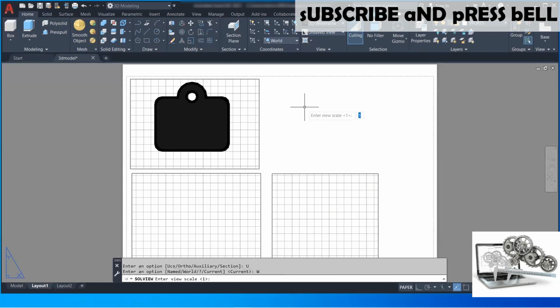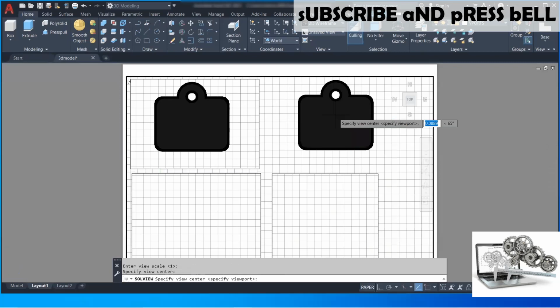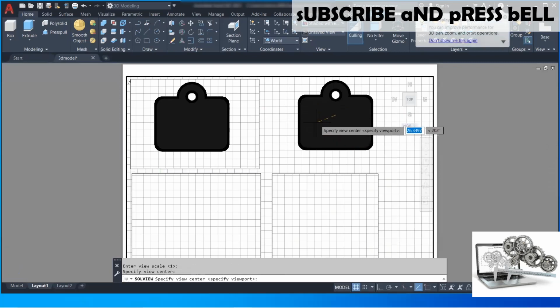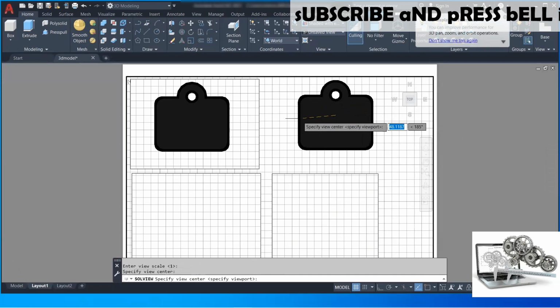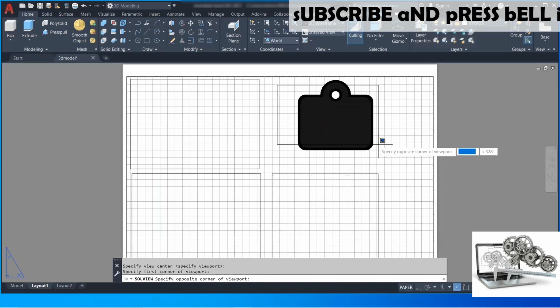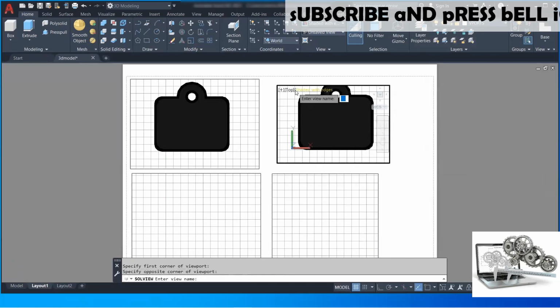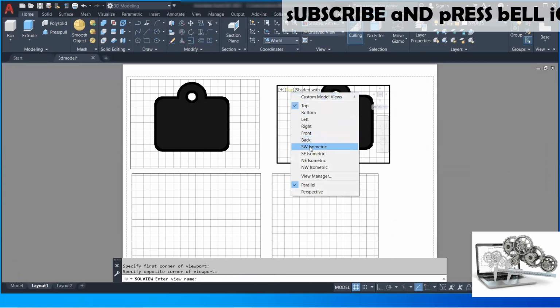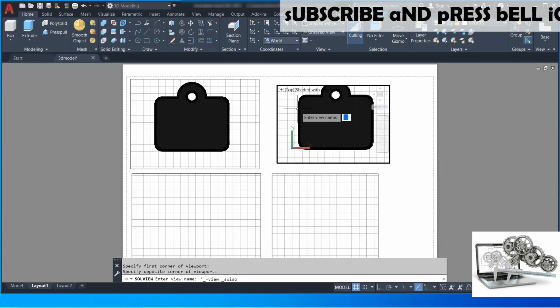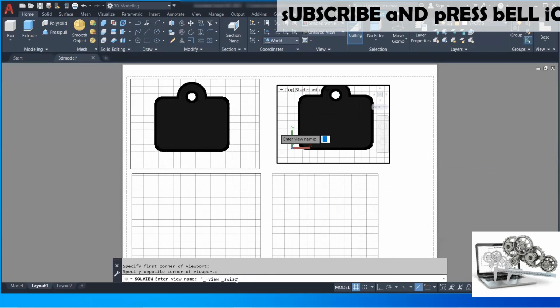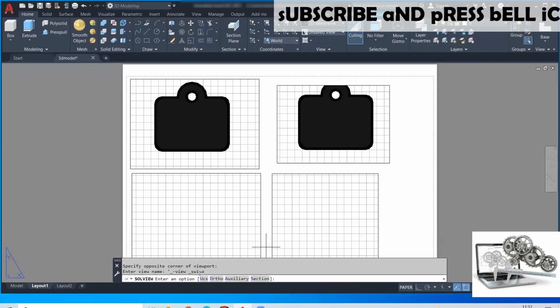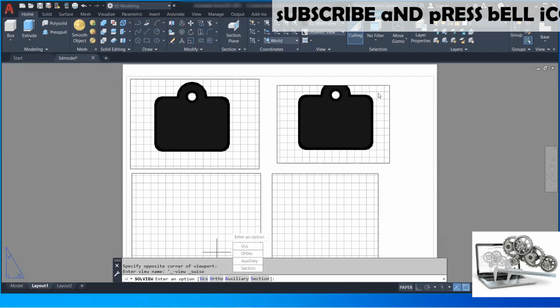Now I want one isometric view also, so we'll go with the UCS mode again, and then I will select World, and then I will create one more viewport here. For this I will give the name as ISO. The process remains the same. Name has been given as ISO view. Press enter key. Okay, all things are done.